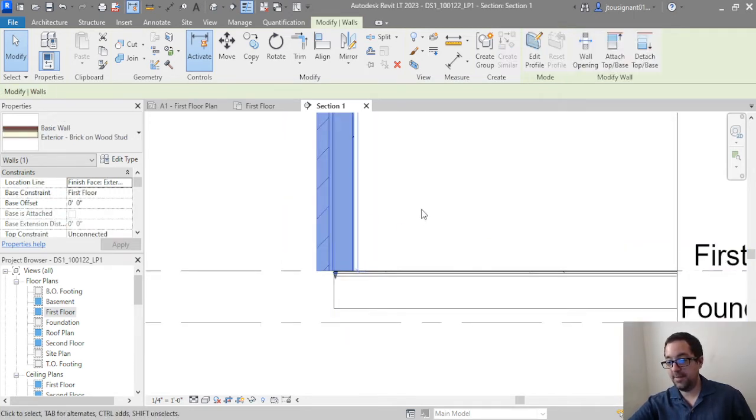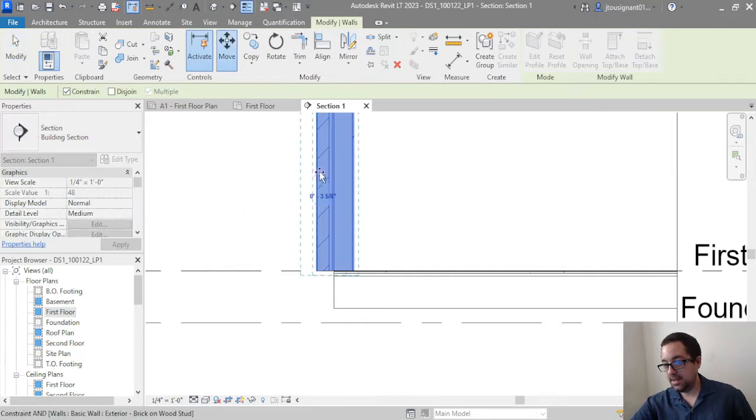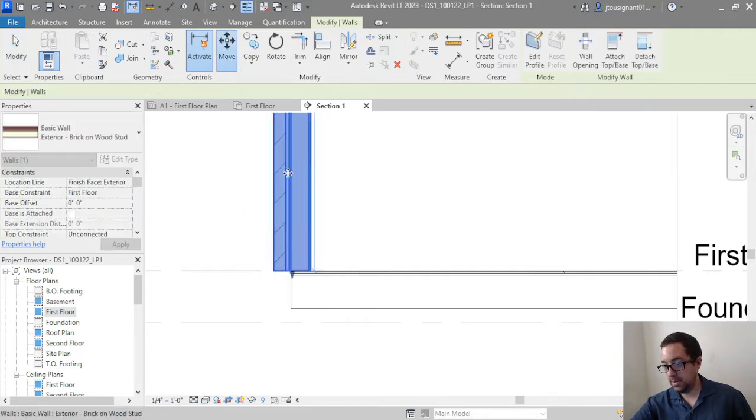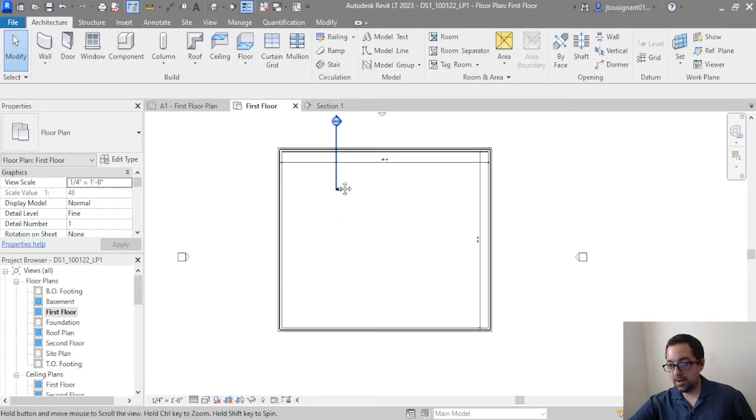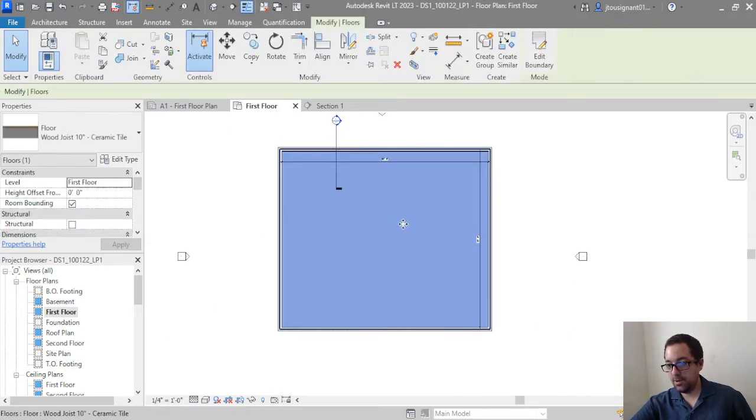and that's why the exterior part of the floor lined up with the exterior part of the wall. And if I click this wall and move it to the left, you'll see that because we join these two by doing the pick wall tool, that's going to automatically join those two, and that's going to make them extend into each other like that. So we've got our walls in, we've got a floor in.